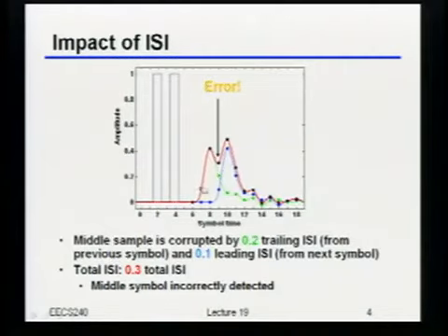That's actually correct. But I want a very simple, physical, intuitive answer. Why is it perfectly okay that some amount of the signal starts to arrive here before the main thing actually gets there? It takes time to charge capacitors. Okay, that's kind of true, but what I'm getting at, the reason I'm not breaking causality, is that I launched the energy at this time, right? So the fact that some piece of it arrives over here, as long as that's after this, that's totally okay. You're right, it takes some time for things to settle, and if that time is large enough, it can take longer than your bit period to actually reach the maximum signal amplitude. So that's absolutely correct.